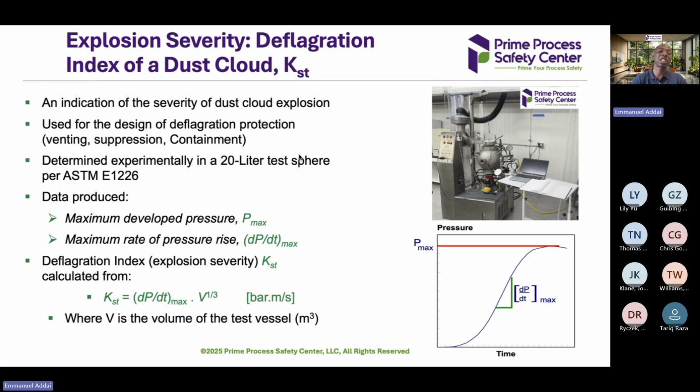The other aspect, which is tertiary basis of safety. So let me start again. We have the primary basis of safety, which is prevention of explosion through removing of the material or staying below the explosive concentration or using oxygen as inert. And the secondary is eliminating various ignition sources such as electrostatic discharge, and you need to know the MIE, or hot surface through friction. You need to know the MIT and the LIT.